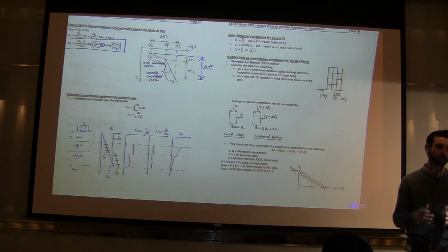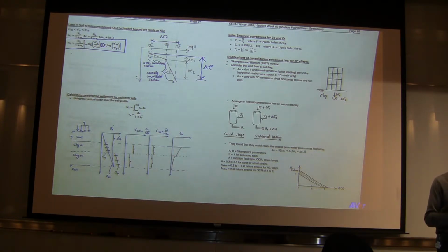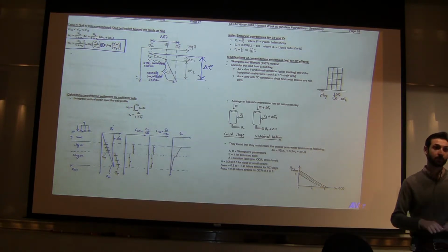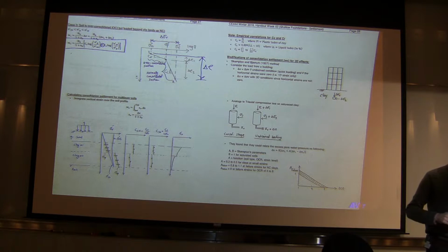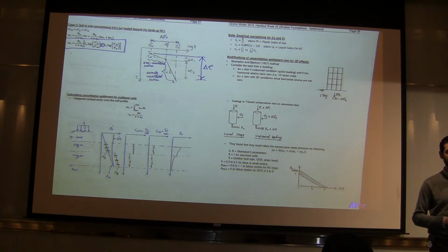Is it the settlement that is going to define the project, or the bearing capacity, or a slope stability issue? Based on that, we can convince why spending more money on site investigation can reduce the cost for the client in the long term. And sometimes it doesn't, and who wants to spend money on something that is not going to change the final answer.